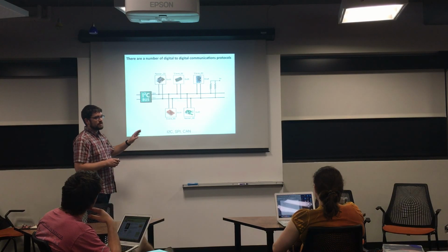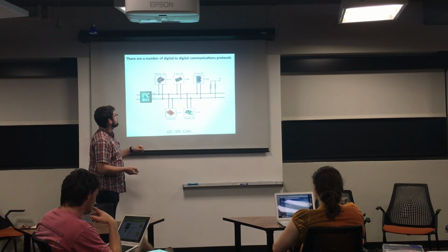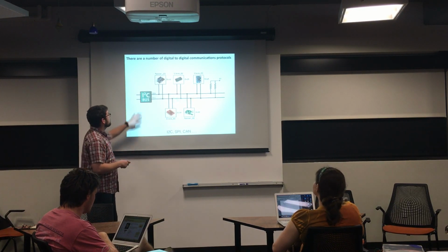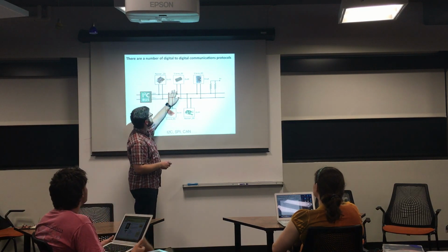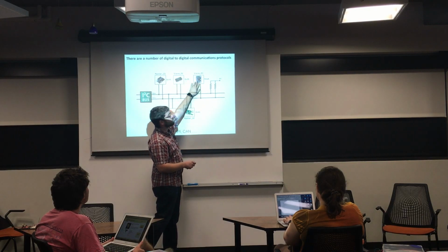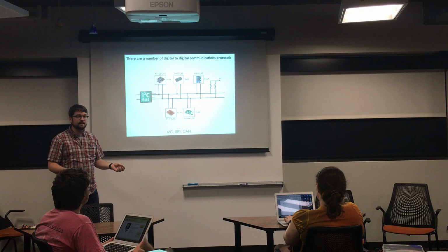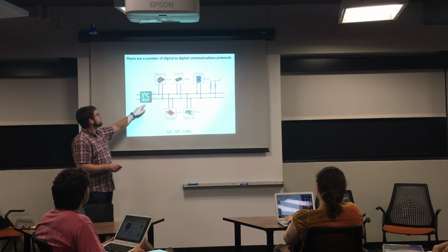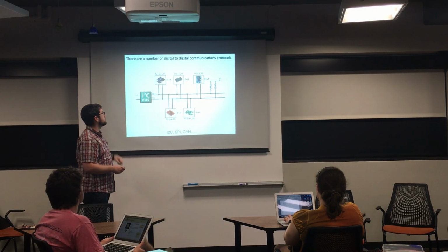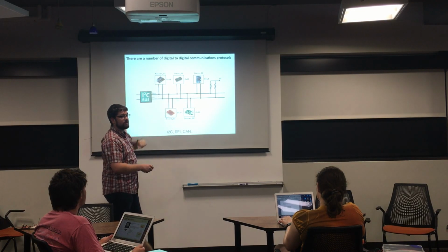But there are transducers that talk in a digital format, and there are a lot of different protocols, but the idea is you have your microcontroller or your computer or whatever the master device is. In this case, the master device is an Arduino. And you've got a bunch of sensors that are all on the same bus. Remember, a bus is just a set of interconnected things that share a conductor. So we've got SDA, which is data, and SCL, which is clock. We'll go over that more in a second. And in this case we've got 4 sensors on this 2-wire interface.